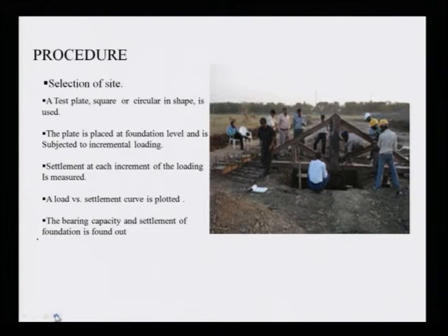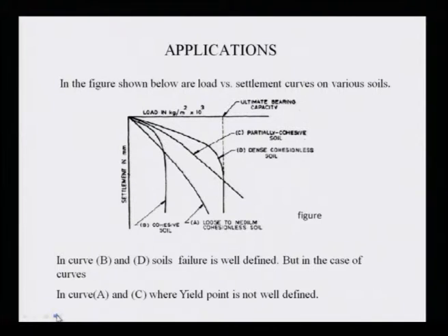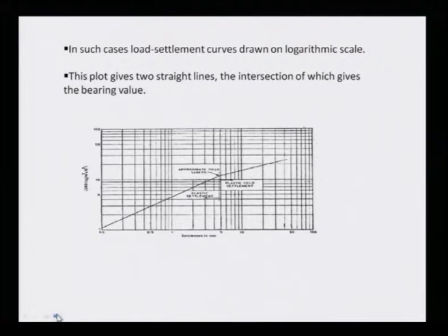Now look at this figure. In the real field there is a loading platform, and a pit has been made from here to here, and this is the loading platform on which the plate load test has been carried out. The photograph I put in directly. This has also been discussed: what type of curve you are going to get for cohesive soil, for medium soil, and for dense soil.